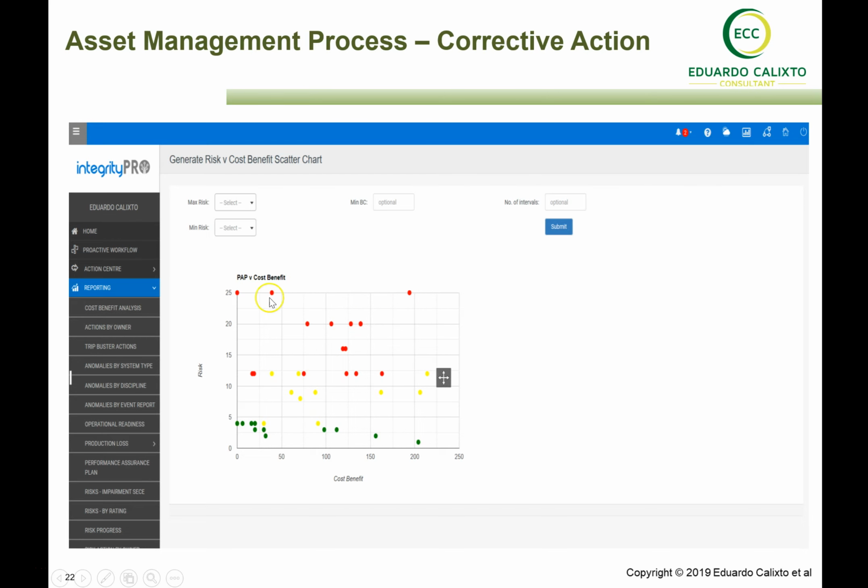In this first line, where we have the higher risk, we implement this one first because it brings the best benefits, the best cost-benefit ratio. After this one and after this one, we go down and start from the right to the left again, right to the left. That gives an idea of how you prioritize the non-tolerable risks.